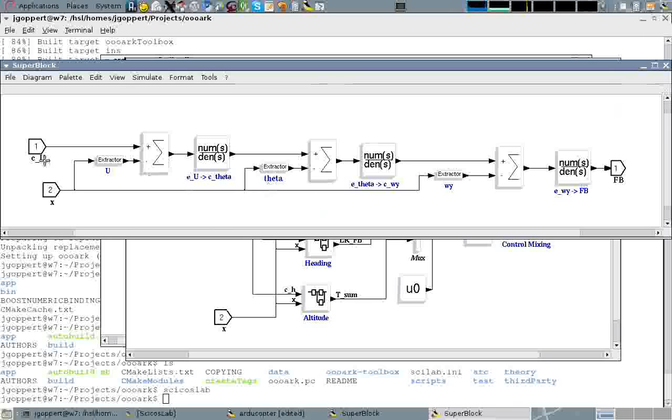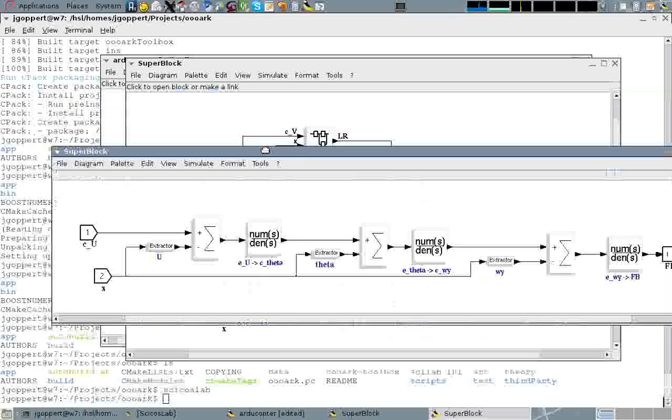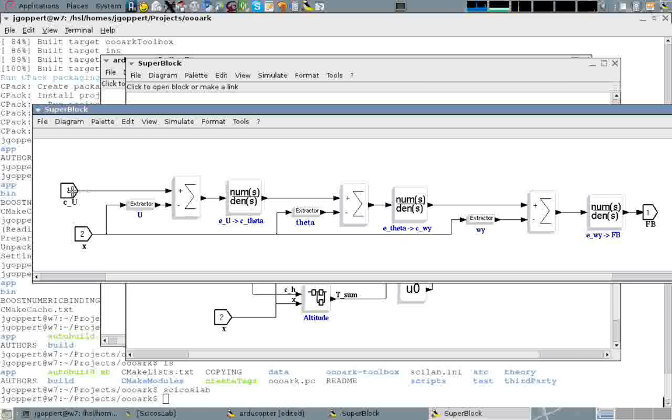Okay, so then it's actually front minus back, 0 to 1 on motors. So then you take in the command forward velocity, you fed back the forward velocity, that gives you an error in forward velocity. So this transfer function is from forward velocity error to theta, which is your pitch angle, and then that's subtracted from the actual pitch.